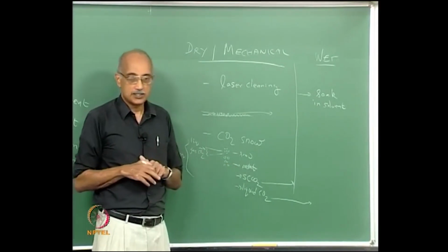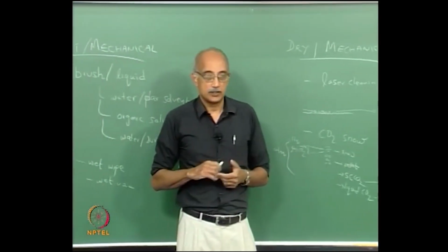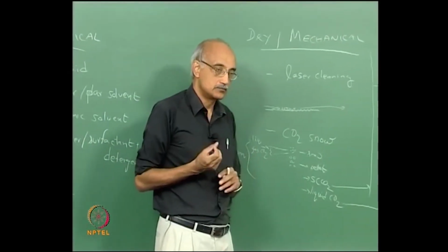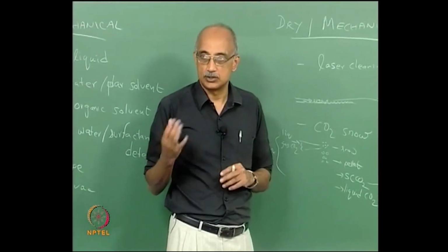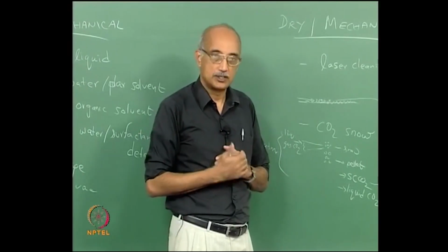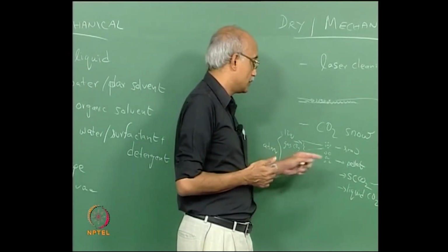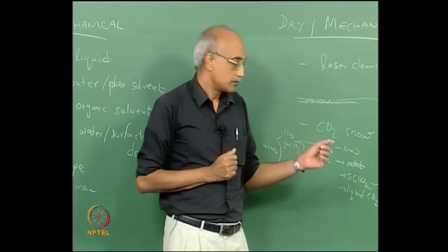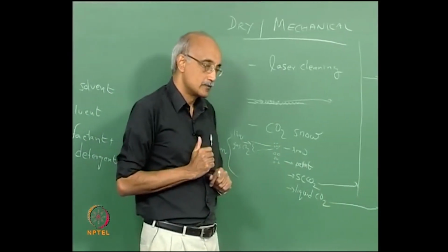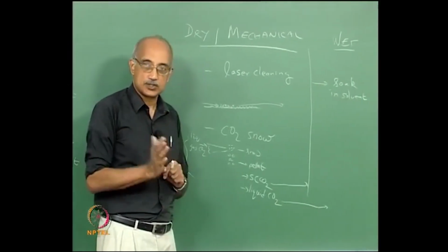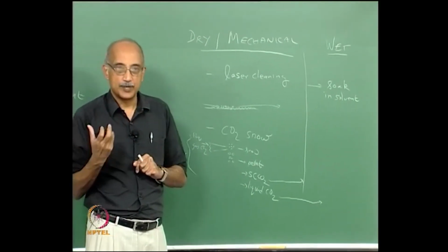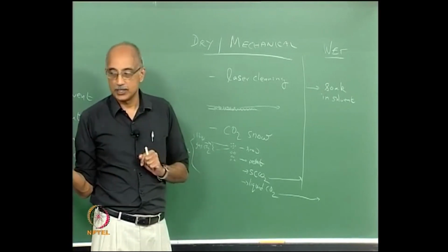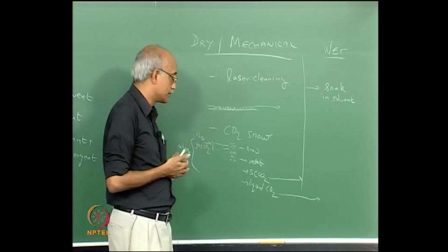CO2 pellet cleaning is somewhat like the abrasive blasting that we talked about earlier. So, instead of using abrasives like alumina or silica to do your blasting, deburring and so on, you take carbon dioxide pellets and do it. Now, the advantage of carbon dioxide pellet cleaning is it does not cause surface damage to the same extent. The hardness, the abrasiveness of carbon dioxide is much lower compared to commercial abrasives that you might use otherwise, and also